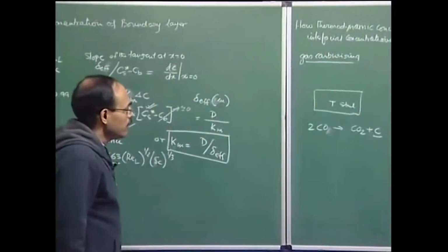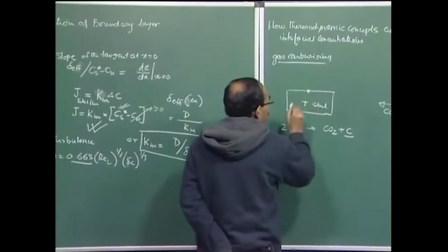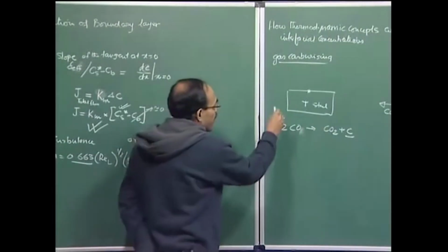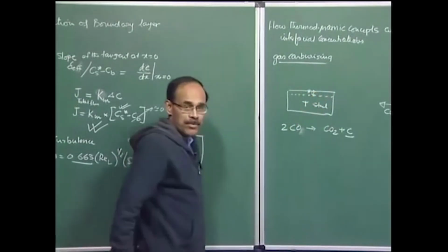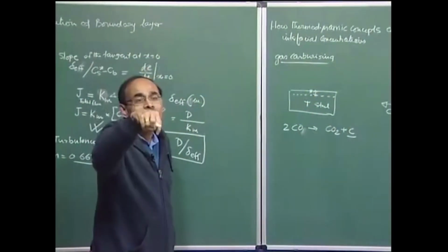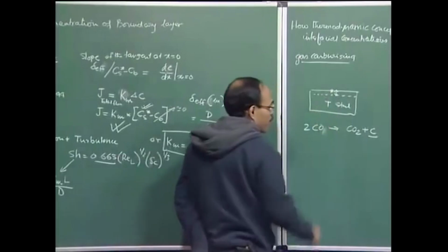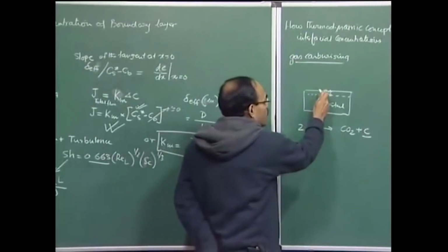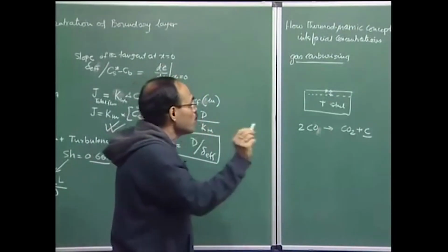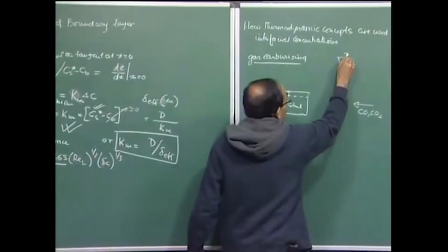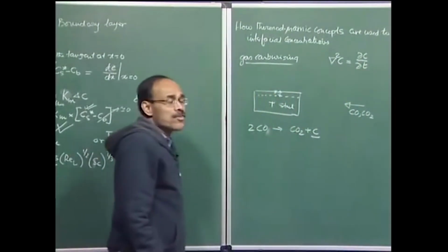Now, in these cases, if you want to find out the rate at which carbon is diffusing, or the rate at which the case depth, meaning the depth through which carbon is penetrating, noticeable carbon penetrates. So, if you want to calculate this rate, it is necessary for us to have the surface concentration known. Why is it necessary for us? Because if you remember, I have told you that we have to solve this equation in order to find out the concentration profile of carbon.